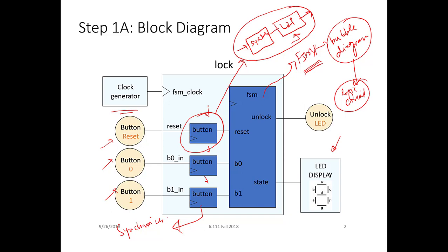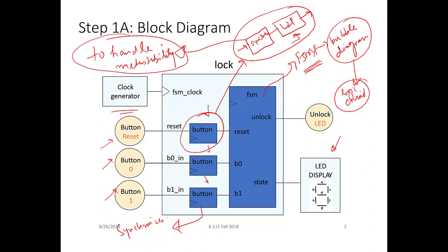So what is the function of a synchronizer? A synchronizer is there to handle metastability. If you remember, when we were designing the flip-flop, we discussed the problem of metastability, and we said that the earlier computers used to hang a lot because of metastability.